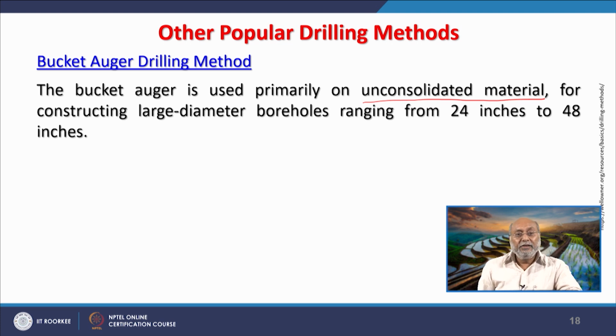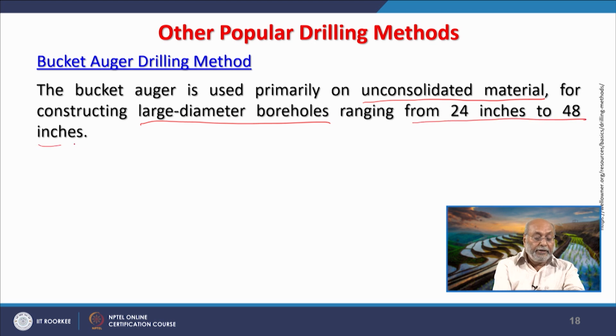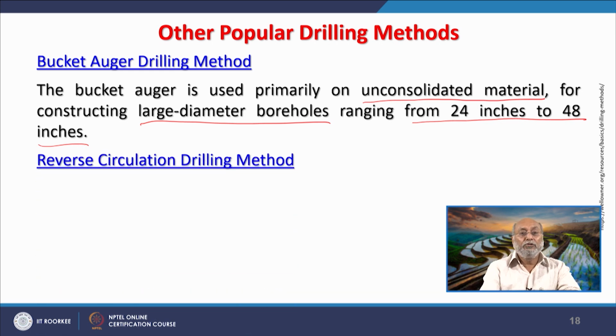And this bucket auger drilling method is good if we are going for large diameter borehole construction, ranging from 24-inch to 48-inch, big holes. But it is only possible in case of unconsolidated material like the Indo-Gangetic plain.